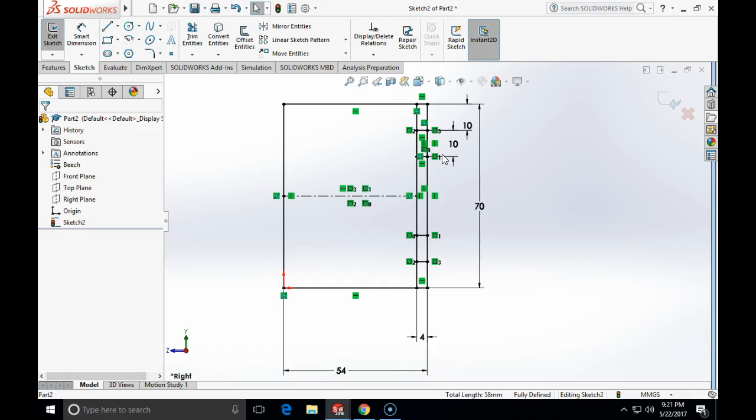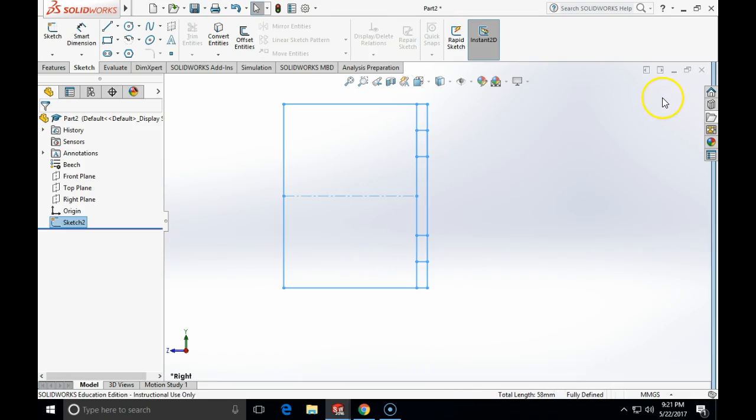Now, this is kind of a complicated sketch. So what I want to do with this sketch, when I extrude it, is choose this area here and only the area inside the tabs. I will not choose the entire sketch. And I will extrude it and create a single extrude. So, okay, I close the sketch by clicking on the check mark icon next to it.